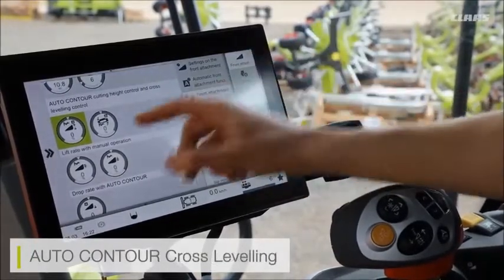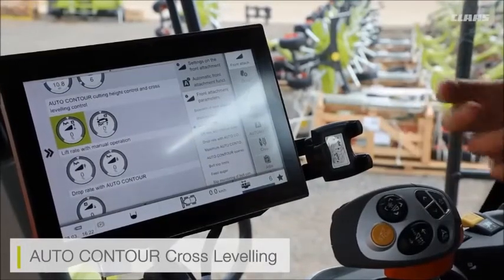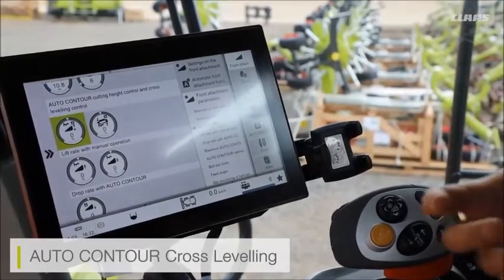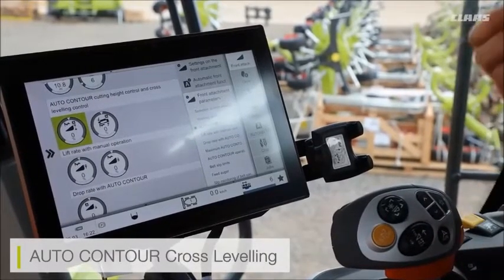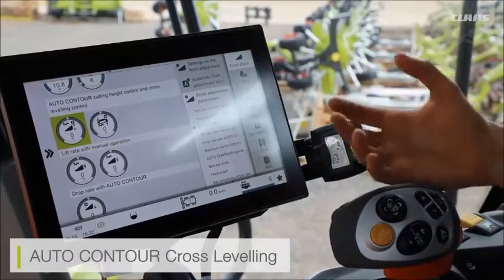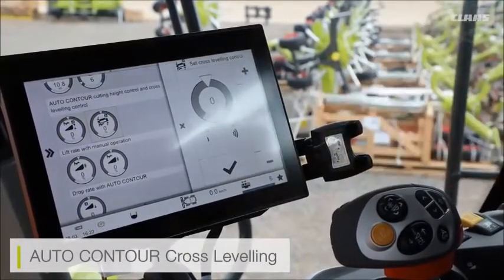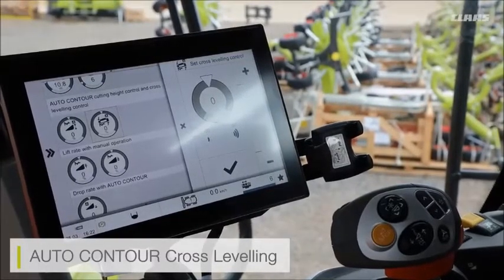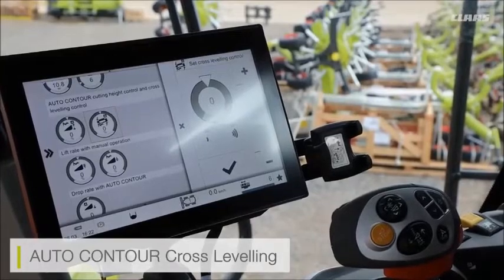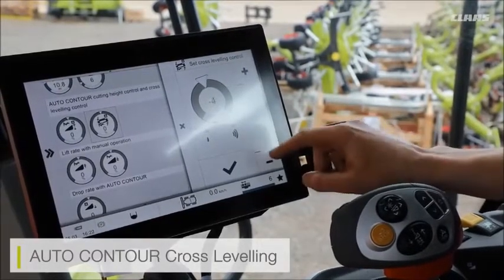I can then also adjust the sensitivity of my cross leveling. So again, our cutter bar is using auto sensor bands if it's in the rigid mode, and that is looking at the sensitivity of these auto sensor bands when cross leveling the cutter bar. So if I find that my sensitivity is set too high, I will start to see the likes of a wavy effect in my crop stubble. So maybe my cutter bar is reacting a little bit too quickly or a little bit too often for my liking. I can then come in and turn this sensitivity down.